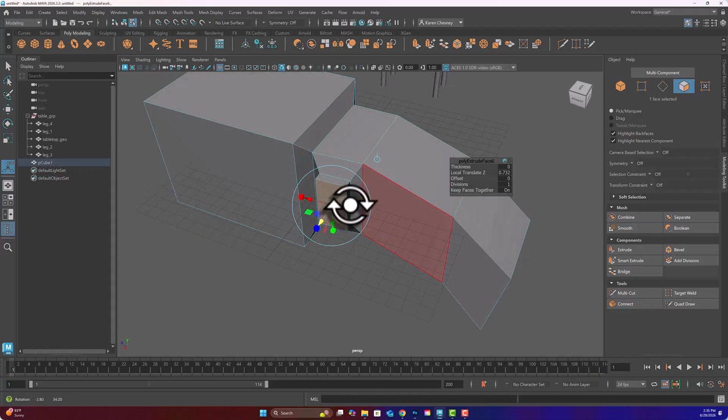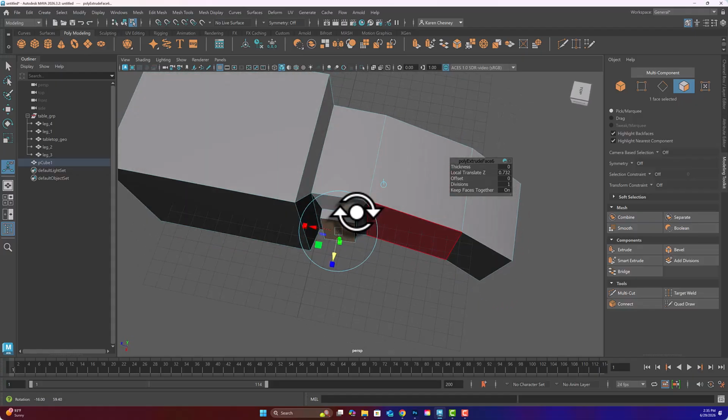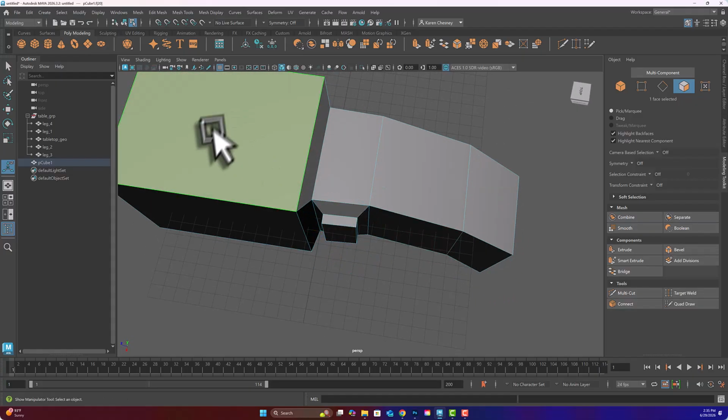Let me show you what happens if you extrude but don't move something. So I grab this face and I hit extrude, and then I'm talking to my friends. Oh my God, can I tell you about Brenda? And I don't do anything to it. And then I'm like, oh, I don't remember if I extruded or not. I'm going to extrude again. It doesn't yell at me. It doesn't give me any warning. It doesn't look like anything happened. But what happens is now I have my original face, an exact duplicate face, and now another face. So there's like a ghost face in there.